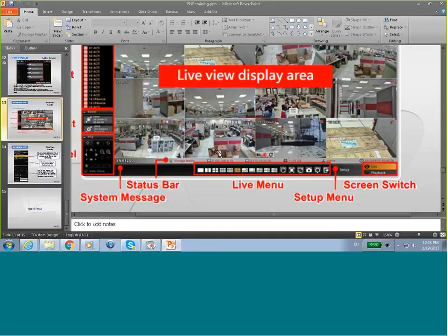So we always suggest using the ENR only for recording, and using remote client computers for monitoring. Secondly, for recording we can have very good quality with the full capacity of the camera. With the live view, we need to downgrade the resolution and frame rate. Then can this be done?